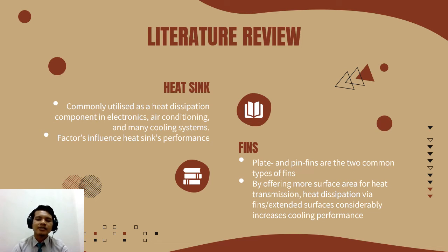Plate and pin fins are thought to be the most cost-effective and easy to manufacture option. There are two types of fins. Plate and pin fins are the two common types of fin from studies that I have researched. By offering more surface area for heat transmission, heat dissipation via fins or extended surface considerably increases cooling performance.